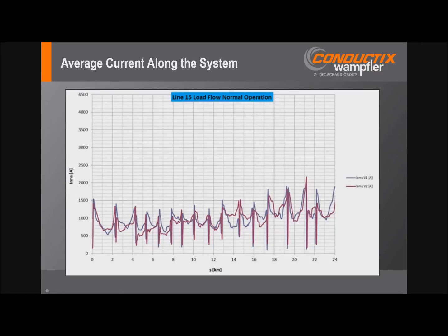In some cases, the specification is that they are not bridgeable, so you're going to have a vehicle typically cross through a switched section that can be disconnected that would require a transfer switch. This is really a power distribution question, and it really depends on the scheme and how these substations are going to react to feeding toward each other and what the implications are.